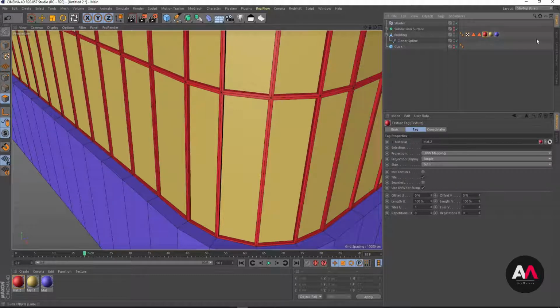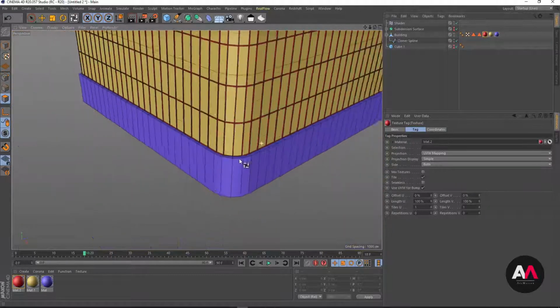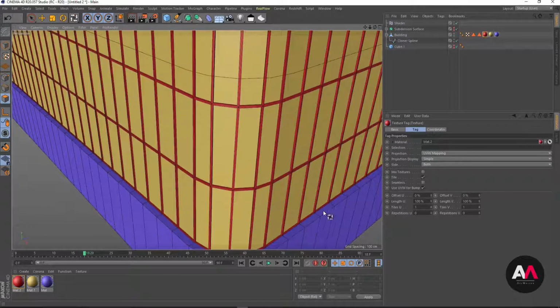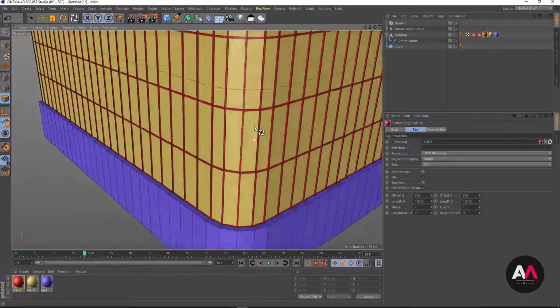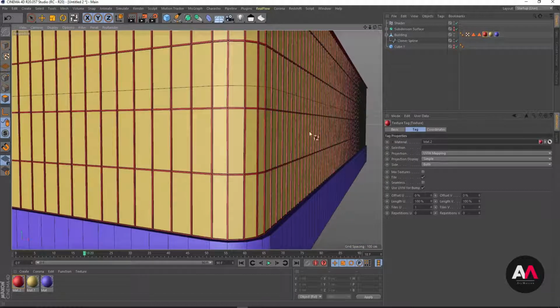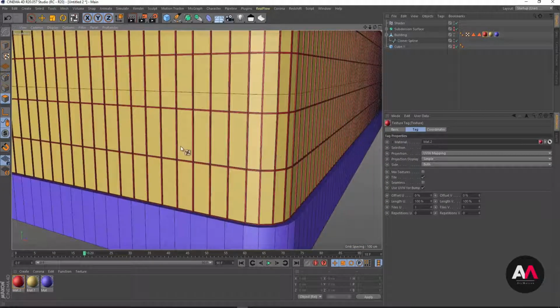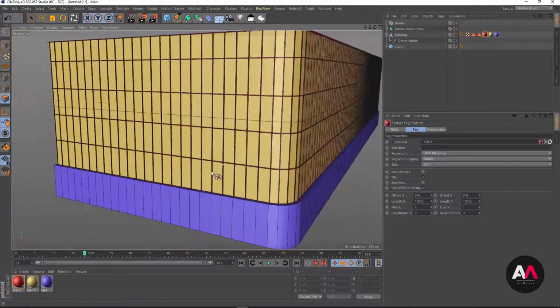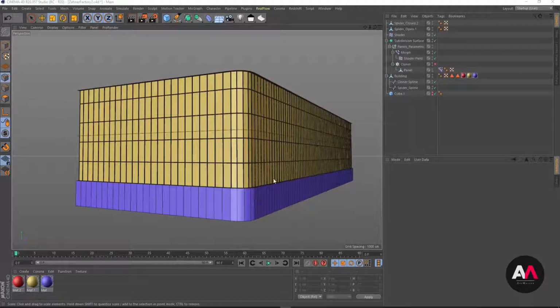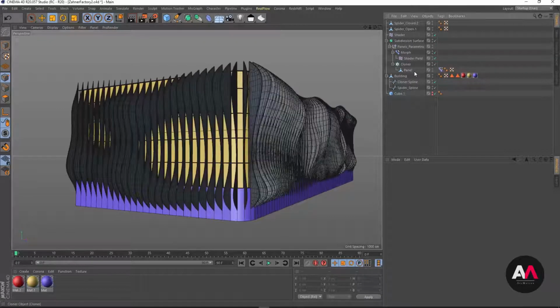It's always like this. So now you see that I have simply dragged and defined the material for later, when I want to assign material to the building as fast as possible. So I don't need to select them individually. Okay, good. Now that we are done with the materials, let me turn on the panels again.